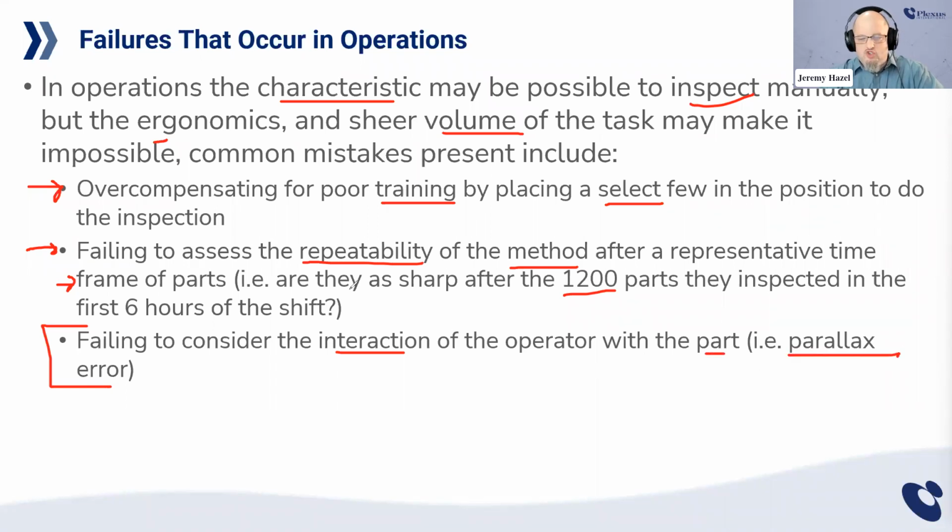This is really crucial because when we do gauge R&R studies, MSA studies on visual inspection, we hold a lot of those things stagnant because we want a good result. You need to practice like it's going to perform in the field. So if it's essential that the light be 15 feet from the table at a 30-degree angle with this particular bulb, we need to put in process controls that don't allow the operator to move the light and thus change